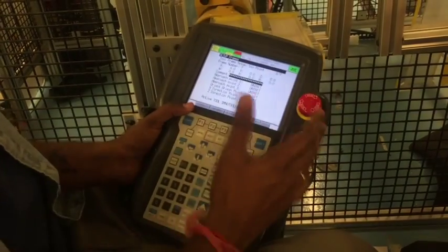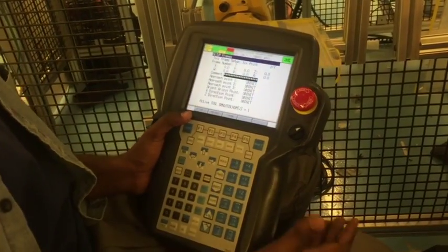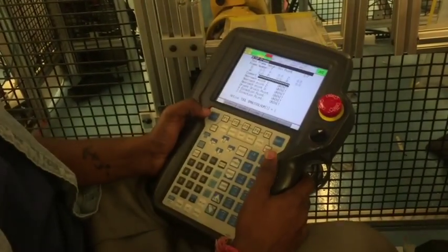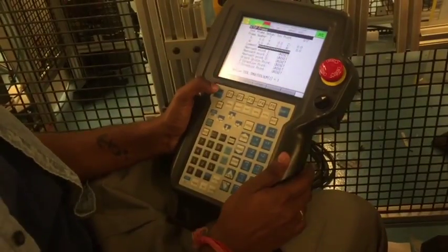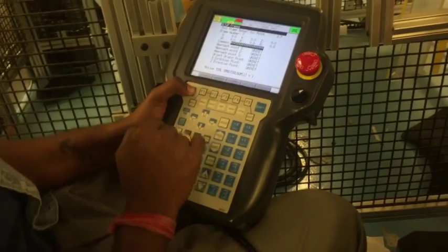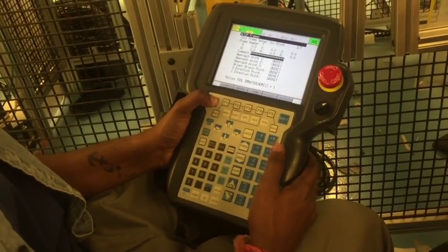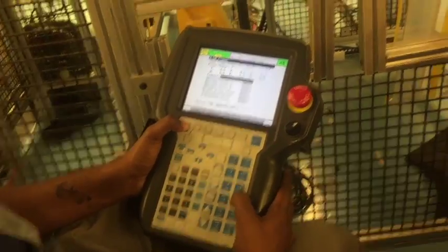As an example of what tool frames are, I already mentioned them, but I'm going to show you a demo. I'm going to operate the robot. I have to press the dead man switch halfway and then release the fault, shift reset, once the fault is cleared. Now I'm going to toggle this.